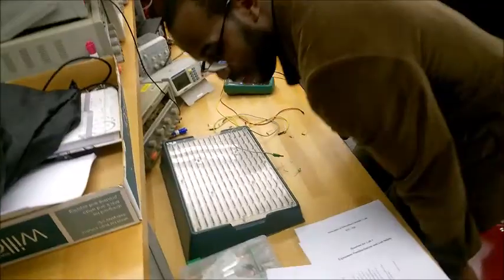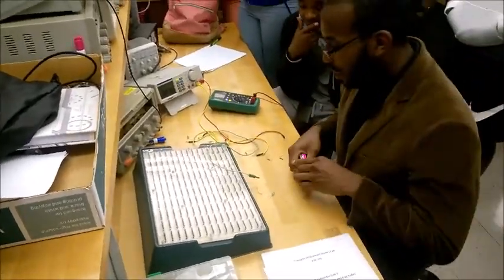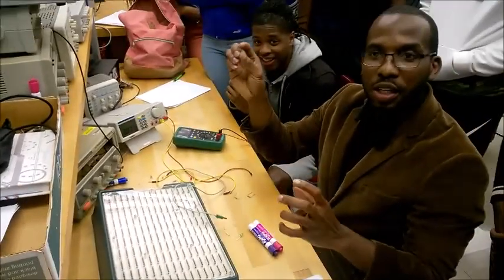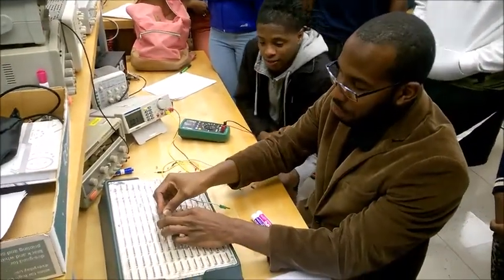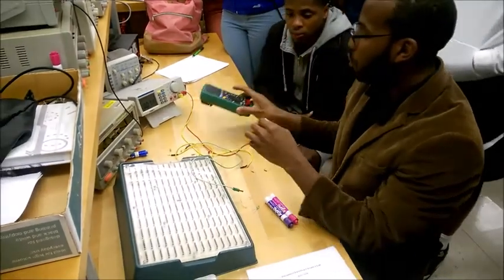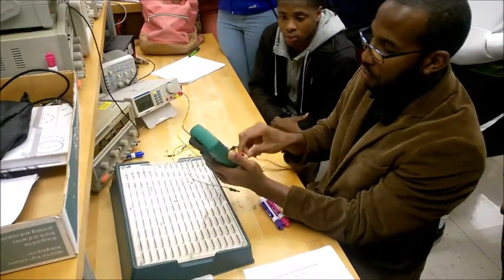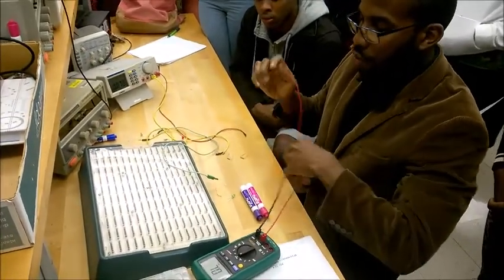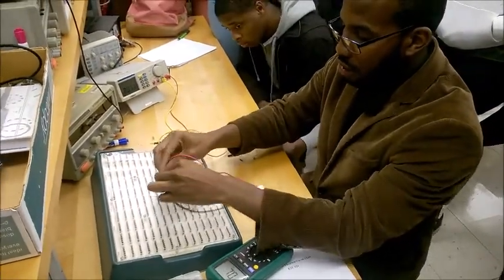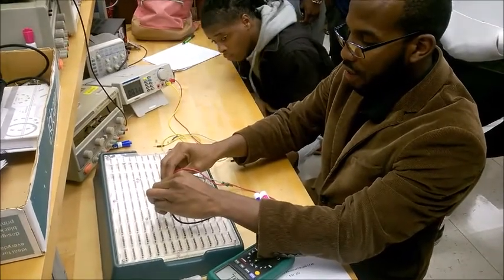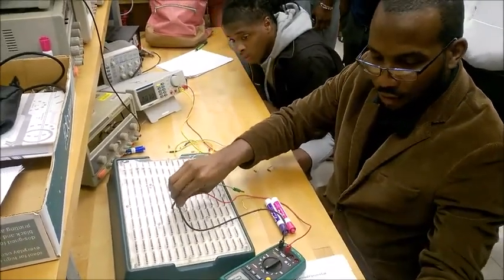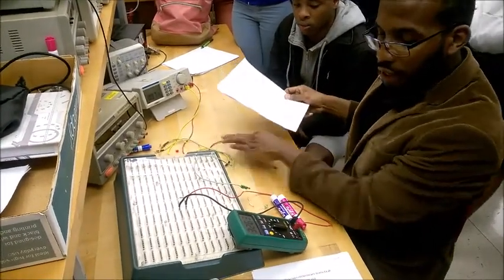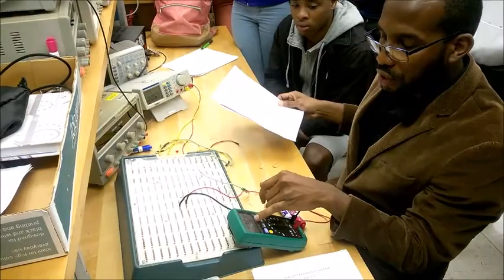Again, this is very simple. You guys should be done in no time. So the first thing we want to do is take our resistor, and each team will get a resistor and an LED, and we're going to measure the resistance of that resistor. To do this, our meter needs to be on ohms, and this port needs to be in the ohms port as well. And then we just put it across the components. The polarity does not matter. Here, the resistance appears on the screen. So the resistance here is 326.4 ohms.